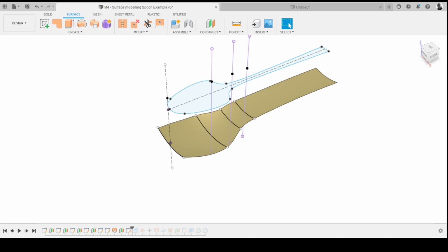You could do. Wonderfully, Charles, you've segued beautifully into next week's session, which is all about the sculpt environment, where I've got exactly that example, where you move from this thin shape into that circular shape at the end. You could do this with lofting, but with that shape, you'd probably have to do it with solid body modelling rather than surface modelling, because if you think of that circle at the end of your spoon and connect that to the right curve at the front of your spoon, that's not really a surface operation, that's more of a solid operation.